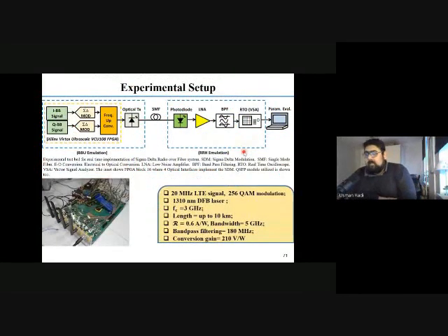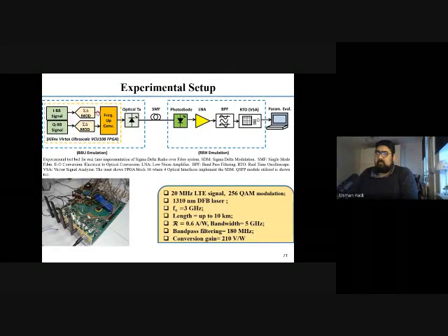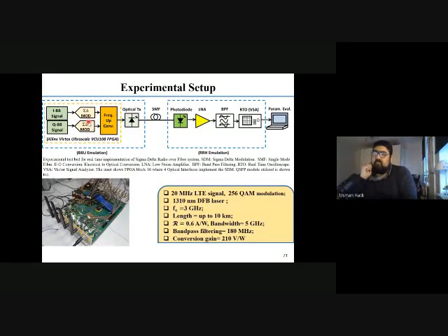So just giving you an idea of how the experimental setup looks, we have the input in-phase and quadrature baseband signals. We do the Sigma Delta modulation by using second order Sigma Delta modulators. I didn't put that slide of what a Sigma Delta modulator is because it's generally known to everyone how it performs, but it is more mathematical, where you have the signal transfer function and noise transfer function. You have the integrator. So I just considered that everyone knows how it looks.